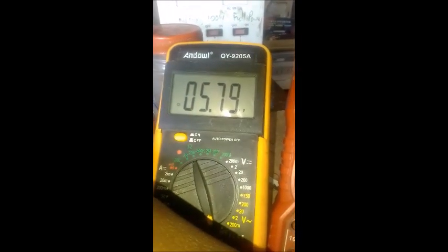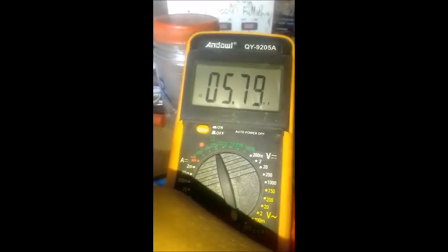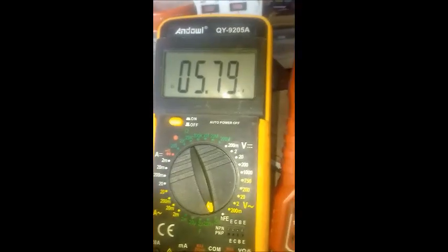Let's choose just one MOSFET here. That's one MOSFET. Not easy to measure. So here is the gate and drain and source together measured, and that's the capacitance 5.79. Okay, that's maybe the tolerance here. I've written 5.81. That's with this meter here, the yellow meter.